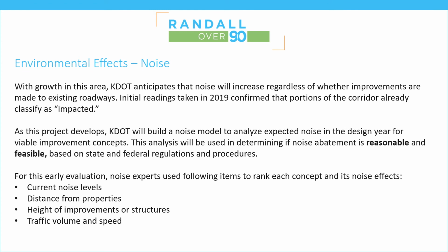Noise analysis. Our team also considered how improvement concepts might impact roadway noise in the project area. It is important to note that with growth expected in this area, KDOT anticipates that noise will increase with traffic, regardless of whether improvements are made to existing roadways. In future design phases, KDOT will build a noise model to analyze expected noise in the design year for viable improvement concepts. This analysis will be used in determining if a noise wall is reasonable and feasible based on state and federal regulations and procedures.